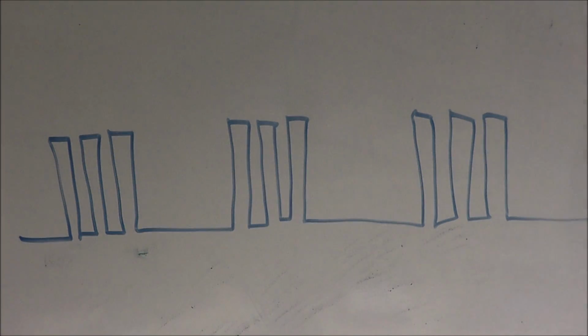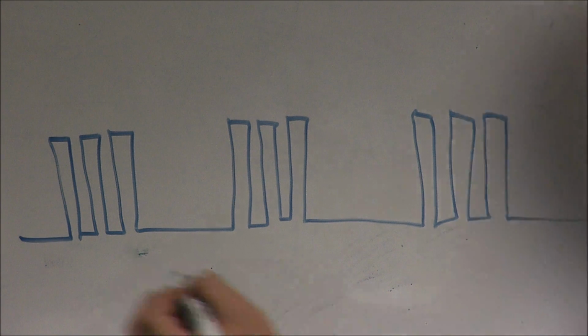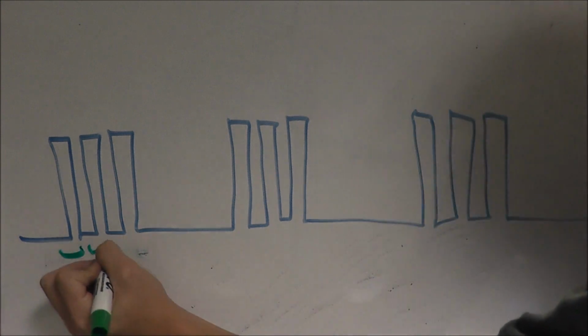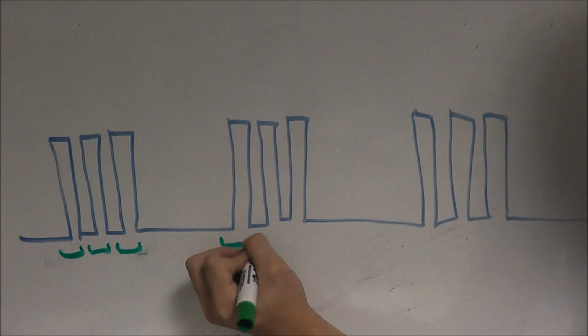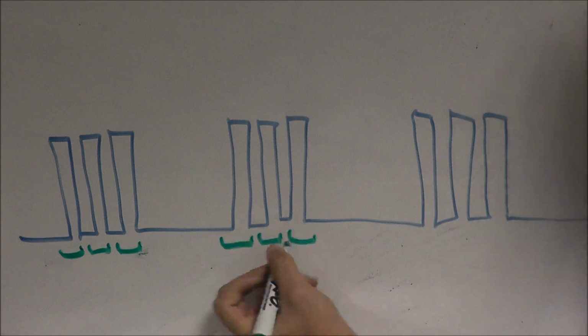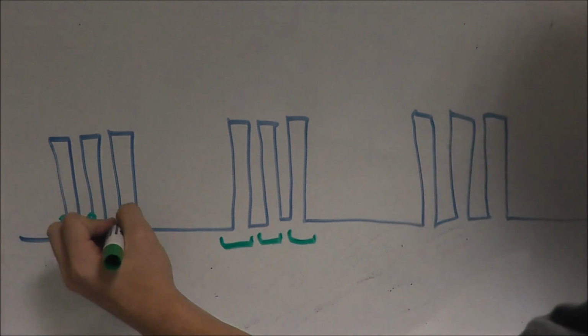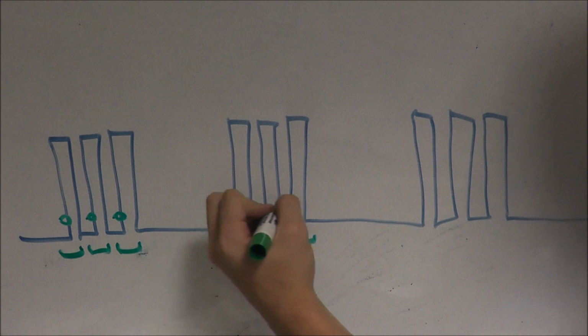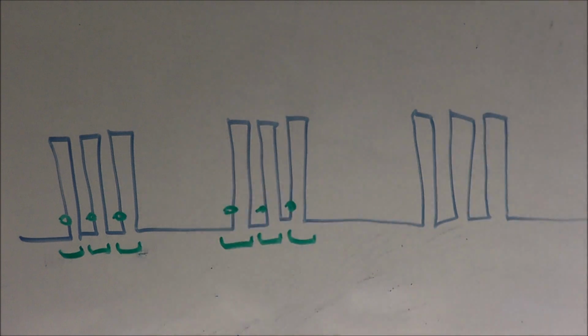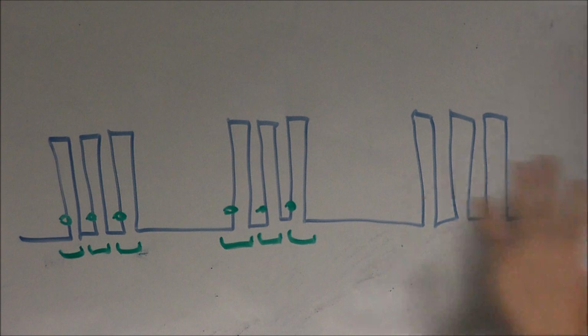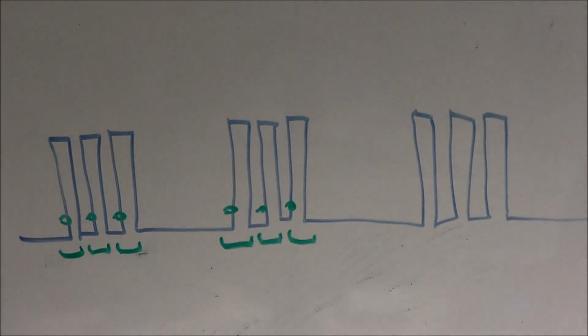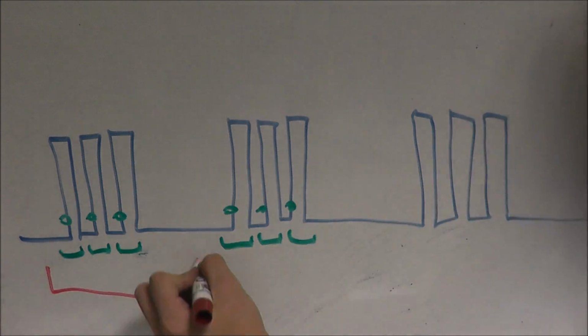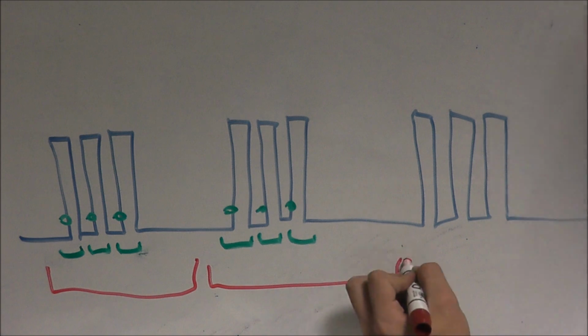Hold-off is also adjusted to obtain stable triggering when the scope is triggering on undesired triggering events. For example, here on a burst waveform, we don't want to trigger on every single rising edge. Doing so would result in the oscilloscope producing a very unstable waveform that would appear to roll across the screen like we saw earlier. We would rather trigger on the first edge of each burst, so we would adjust our hold-off as such.